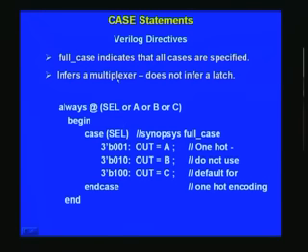For the time being, we will see how this does. So, there is a directive called synopsys full case, full_case. This looks like a comment, but it is a directive, it is more than a comment, right. So, take care that you do not put this as any of your comments. If you do, you will get into trouble, right. What all it signifies for the synthesis tool or even a compiler is that we have given only a partial list here, we have not given the entire thing, but you regard it as a full case. That is what the implication here is. So, just by giving this here, you do not have to list all the conditions, right. Is it clear to you what a full case is?